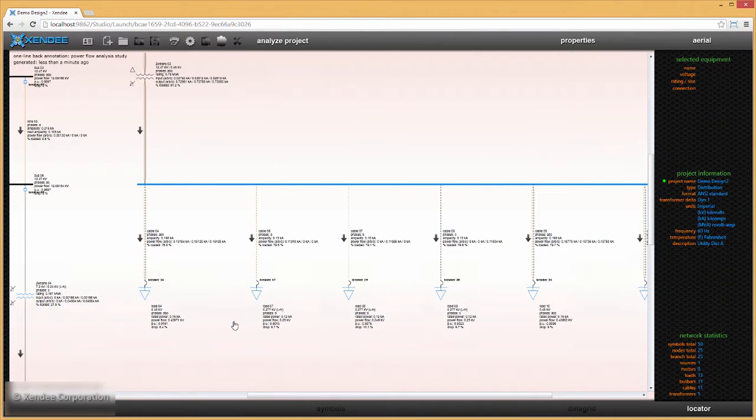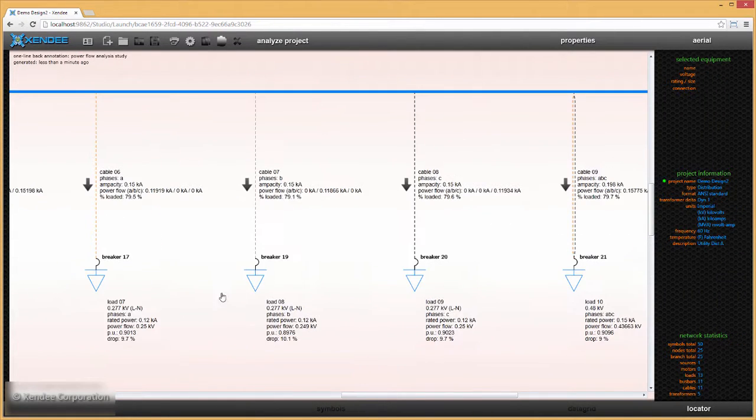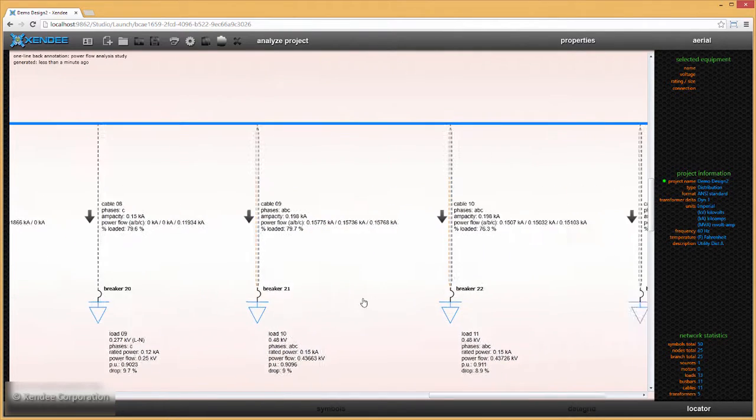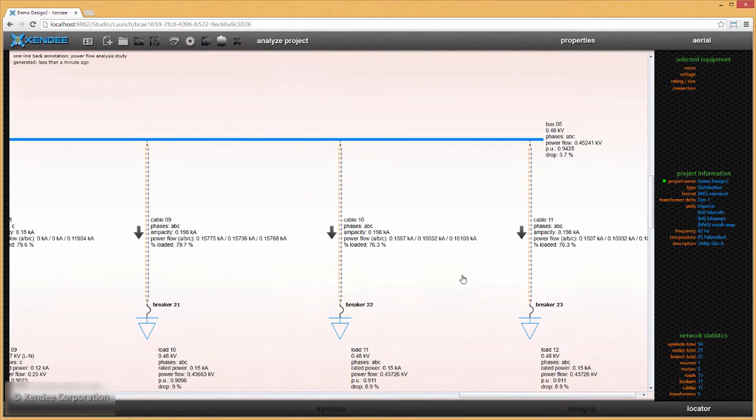Bus voltage regulation is commonly accomplished via load tap changing transformers, which allow the output voltage of a transformer to be regulated, typically in 32 discrete steps, with each step representing 5/8% change in voltage. The objective for implementing LTC control is to hold voltage at a bus at a desired level.